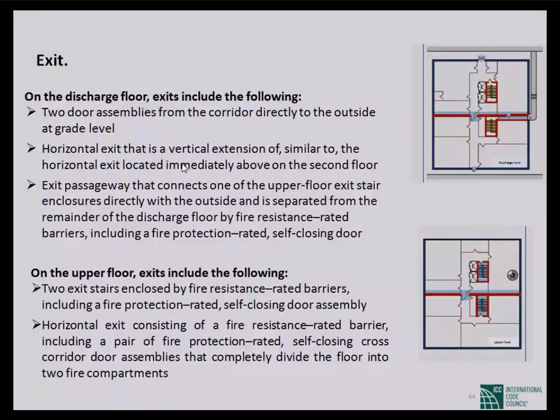Exit passage that connects one of the upper floor exit stairs, enclosed directly with the outside and separated from the remainder of the discharge floor by a rated barrier including a fire protection rated self-closing door. That is the exit of the discharge floor, and in the lower picture you can see the blue line.